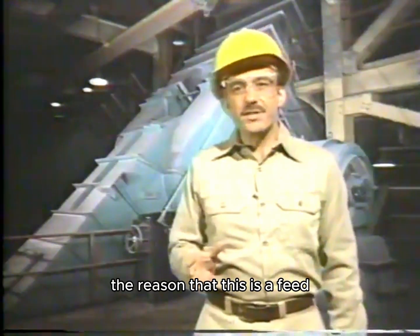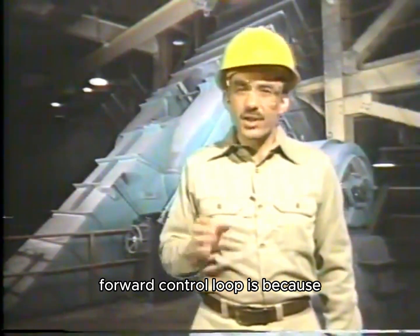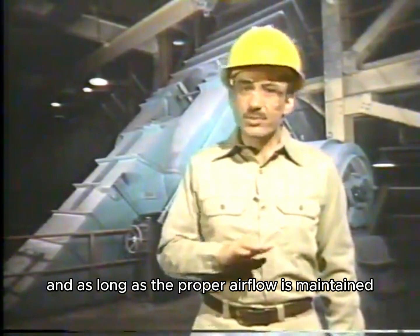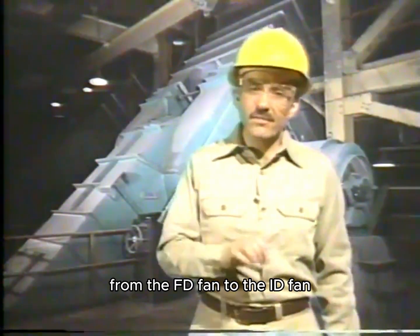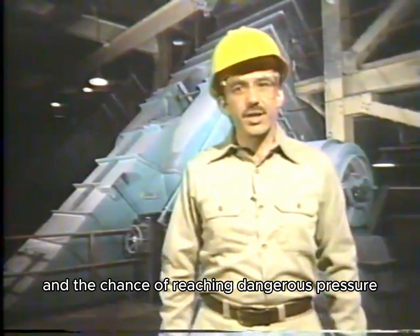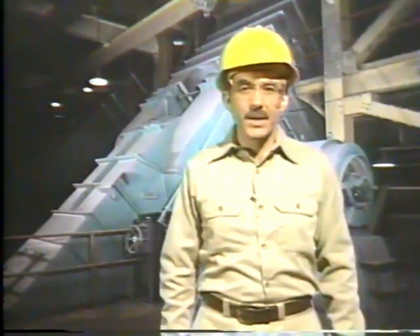The reason that this is a feed-forward control loop is because the control loop works to maintain the proper airflow. And as long as the proper airflow is maintained from the FD fan to the ID fan, then the chance of reaching dangerous pressure levels in the furnace is minimized.